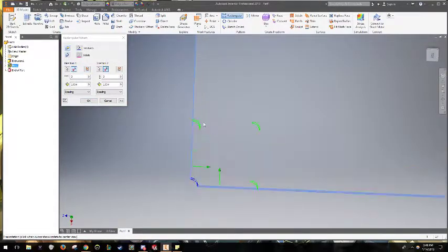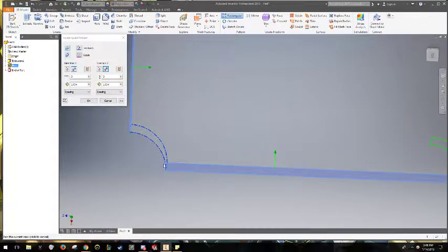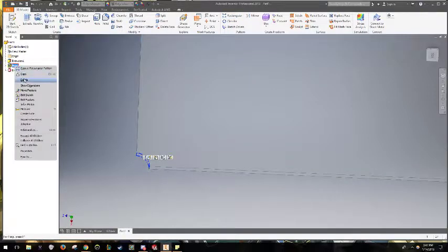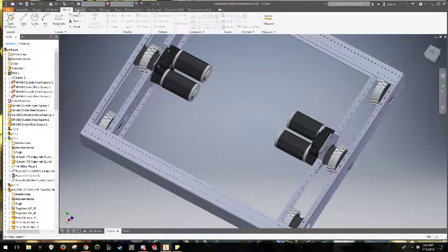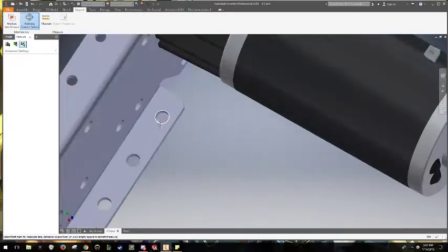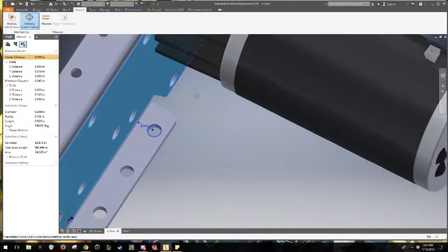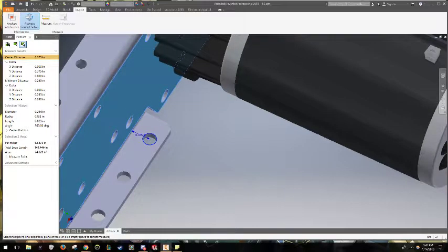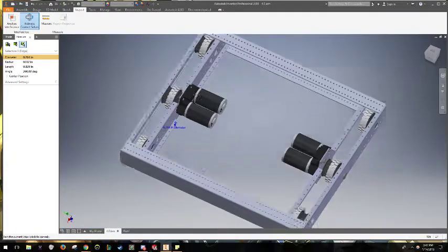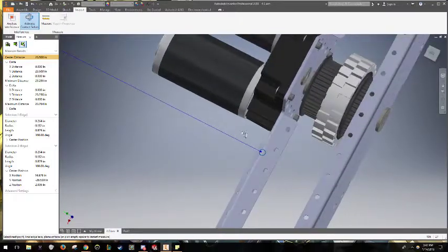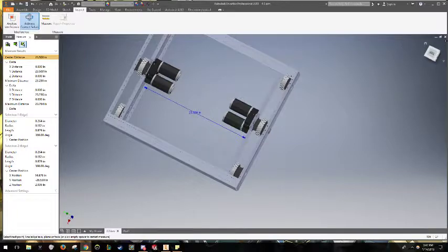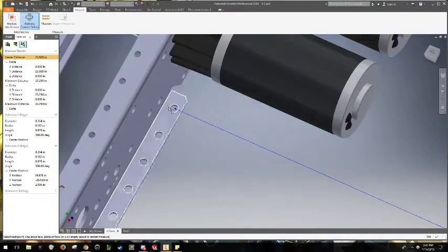Now, see, the issue here is that it's just copying this part of the pattern. I wanted to create the whole entire hole pattern, so I'm probably going to restart now, considering that I messed that up somewhat. So that'll be 24, because I want to have a quarter inch.